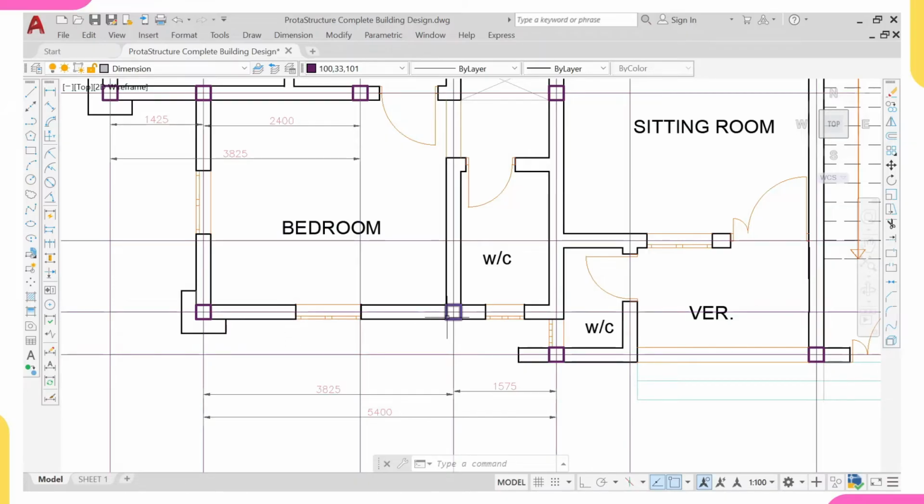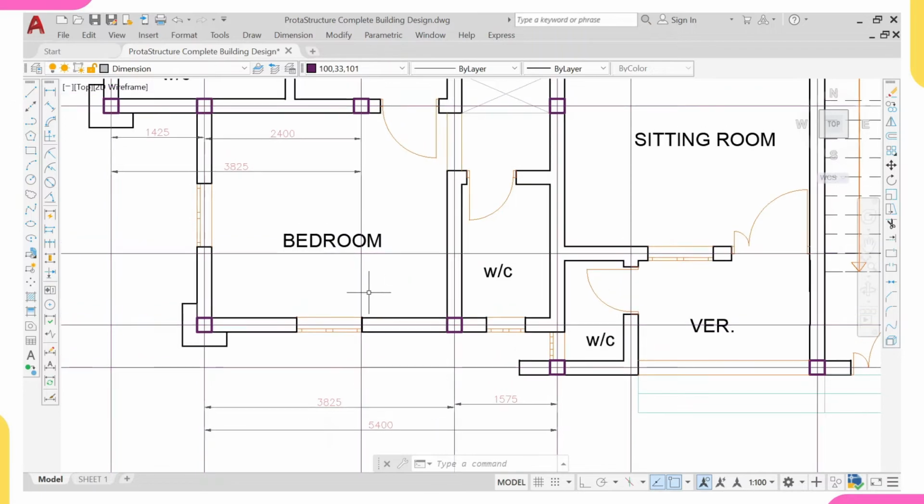Also, another reason why I remove this beam is because this is less than 6 meters. Look at it, it's 5.4. So first, it's carrying a lesser load and it is less than 6 meters. Don't forget what I explained there. Maybe after design now, I'll be having 3Y16 here. If you have 3Y16, it's okay. Yeah, it's still okay.